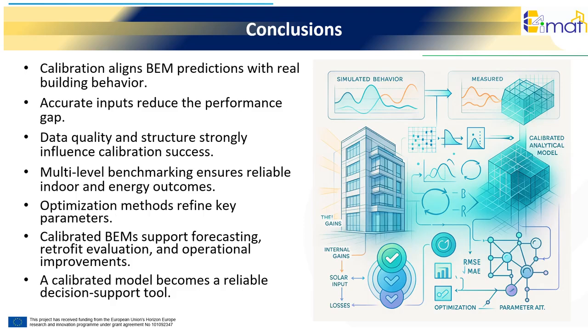This iterative process transforms the BEM from a theoretical approximation into a reliable analytical tool. Once calibrated, the model can support forecasting, evaluate retrofit strategies, improve building operation, identify faults, and guide energy-saving interventions. In essence, a calibrated BEM becomes a powerful decision support system grounded in measurable reality.